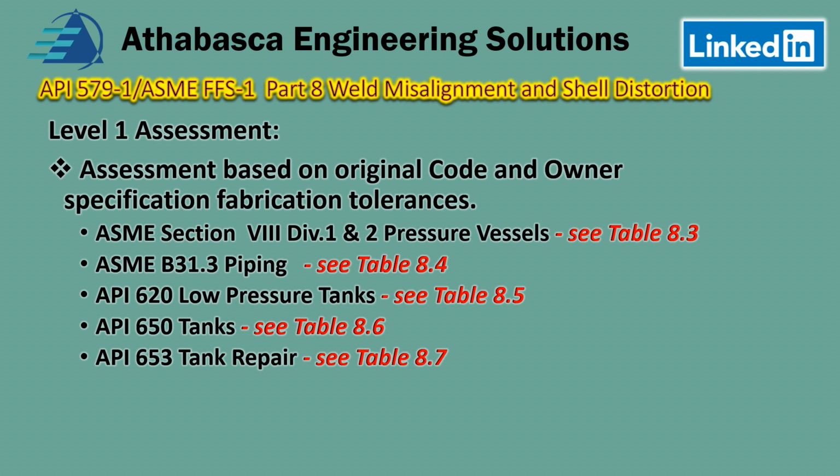Again, these are all values taken from these API and ASME standards as a basis for acceptance. So basically, if you're within those owner and specification fabrication tolerances, then you pass a Level 1 assessment. It's that simple. One note before we go to the next slide: a Level 1 assessment is not applicable to cyclical service.